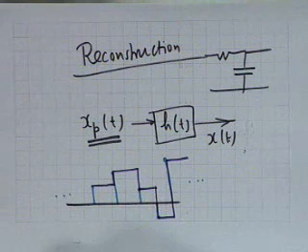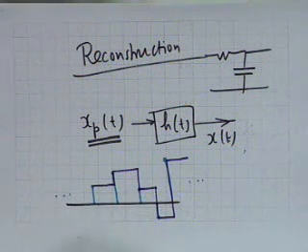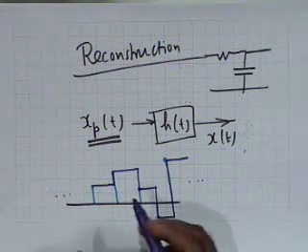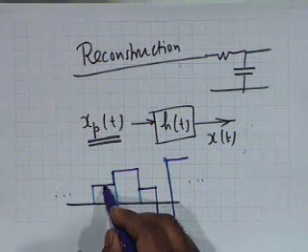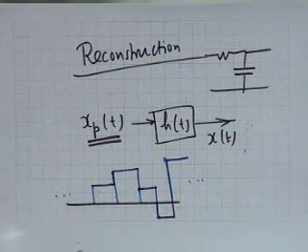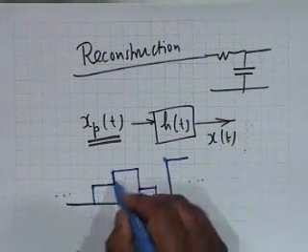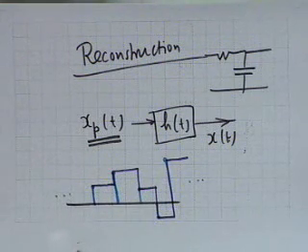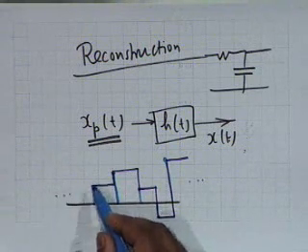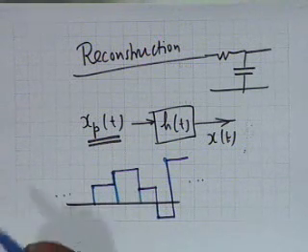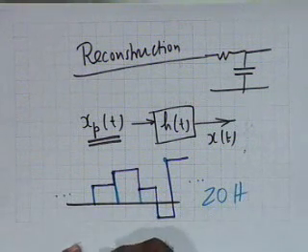So a zero order hold is also an interpolator. That is, what we are essentially doing is we are interpolating the value of the signal between two sampling instants. Only a part is given, only these blue samples are given. In between we have no information. So in absence of information, all we do is we assume that the signal remains the same as at the previous instant. So we are interpolating or we are approximating. This is called a zero order hold interpolator.